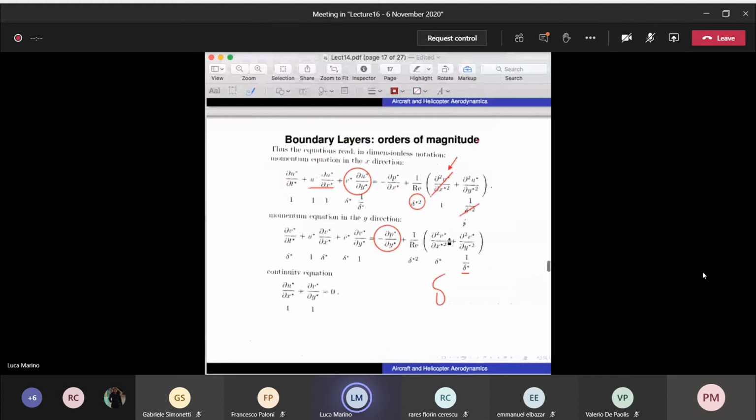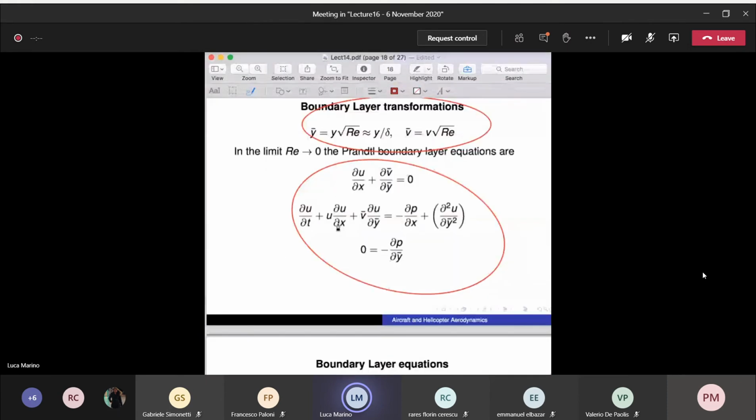Now, our set of equations is this one. The higher order term in U is just for Y. The derivative of U with respect to Y is second order, but the derivative of U with respect to X is just here and here, so first order. So here we have to give two boundary conditions for the variable U with respect to the coordinate Y, and one boundary condition for the variable U with respect to the coordinate X.